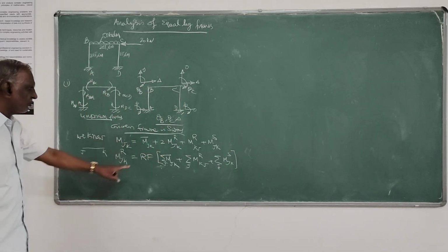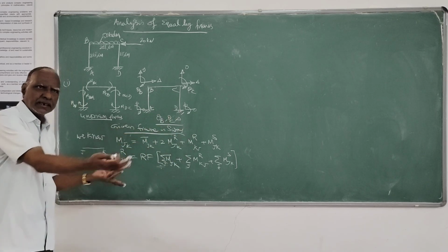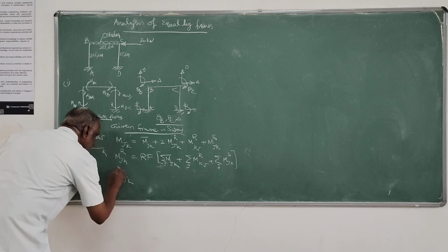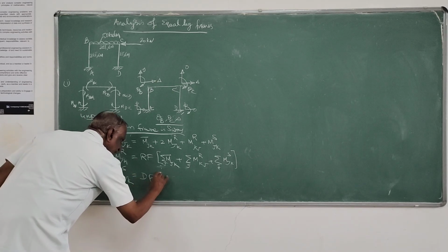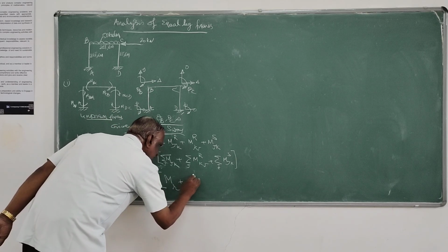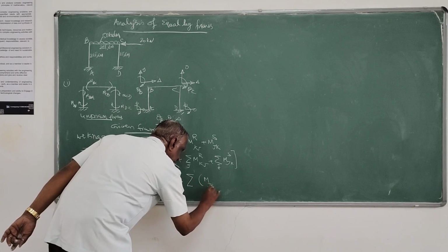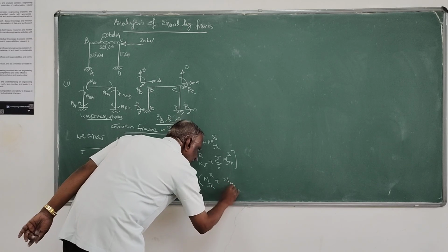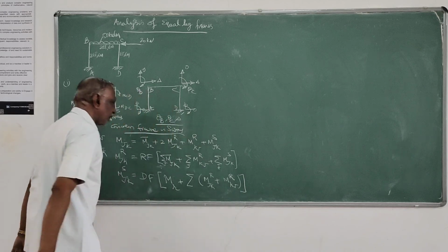So this is the formula for finding either MJK or MKJ. And the sway contribution is given by the displacement factor into the sway moment plus the sum of the rotation contributions of all the members, the near end and far end rotation contributions that you have to take.